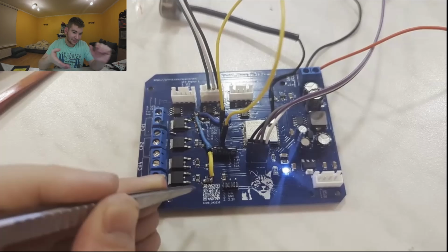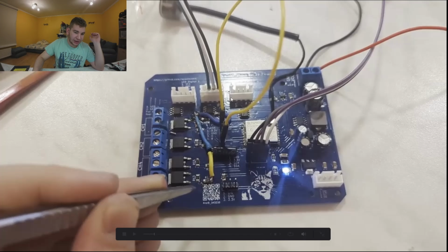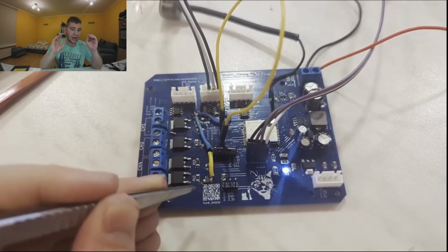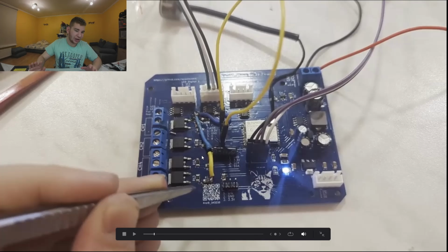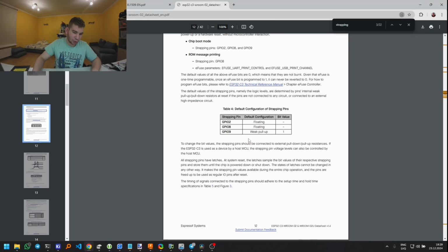Here is Alex from the future, and I'll quickly explain what was happening in the 2 clips before. So in the first clip, the board is successfully flashing. However, it doesn't boot up. And as you can see carefully, we have a pin header here, which has pin 8 and 3.3 volts, and we have a jumper here, which connects them. And it's a requirement for flashing. However, one thing I forgot, and I didn't know about it. Honestly, I would say I didn't know, but I should read the documentation more carefully.